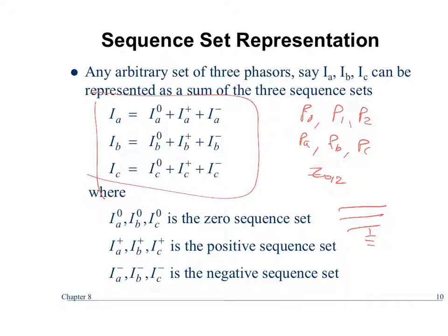if you have a system that you're trying to protect, sort of at a distance, you can look literally at the impedance. What is Z? Is Z within a window or outside a window? If it's inside this window, so if Z is in here, trip. If it's outside, no trip, right?